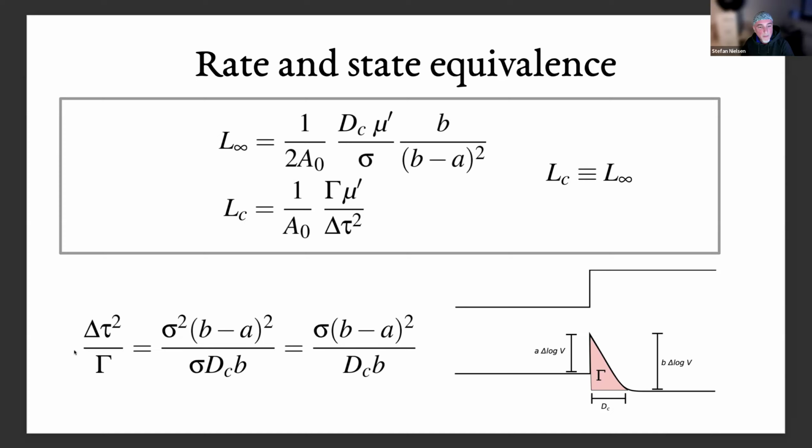But basically, this expression for LC, which is based on energy consideration, and this one, which is based on the rate and state laws, in my opinion, are perfectly equivalent. Although the friction law may not be the same, because as soon as you hit the dynamic regime, you may have enhanced weakening taking place. And all sorts of